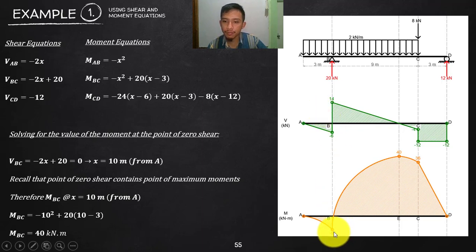Now from your point B going to that maximum, now your slope here, the intensity of loading here, is now positive. Okay, positive, positive, positive. But from a big positive 14, it will be going to 0. So again, what is 0? That is a slope of a horizontal line. So the line tangent to this point here is horizontal. That's why it is a maximum point on the curve. So look at this, a big slope. So a sharper slope.